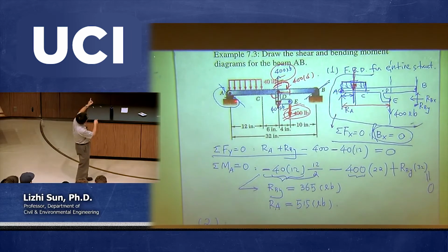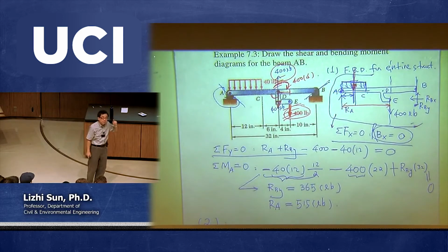Let's say I have a support at this point, and I move the support from this end to here, for example. If there's a real support, yes, you need to separate because there's a discontinuity in terms of force. But this point is at the end already. We are standing at this point and trying to move to the right. So you don't need to say I'm going to cut exactly at point A. A is already cut. That's the edge. So that's why you don't need to cut.